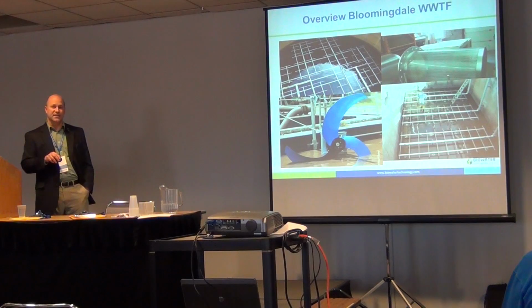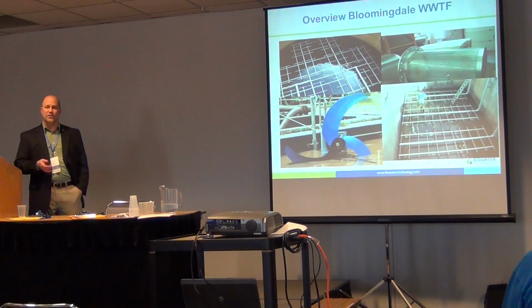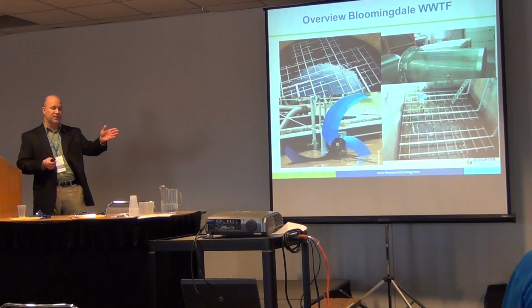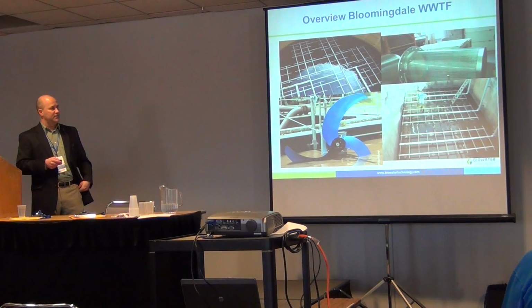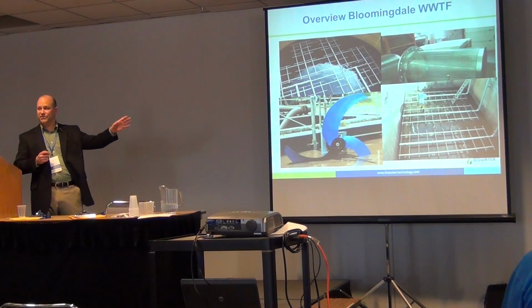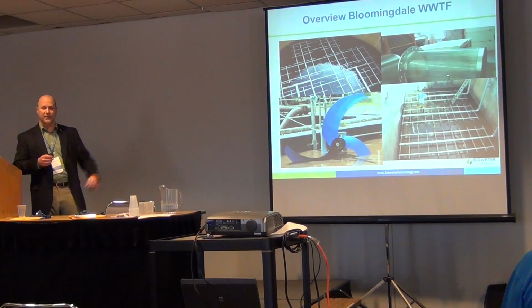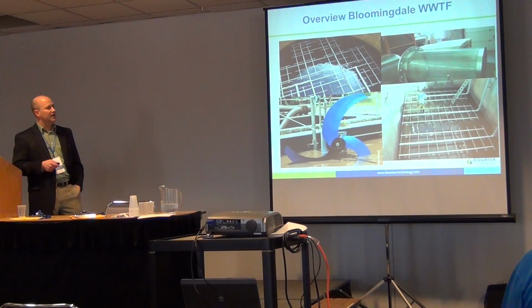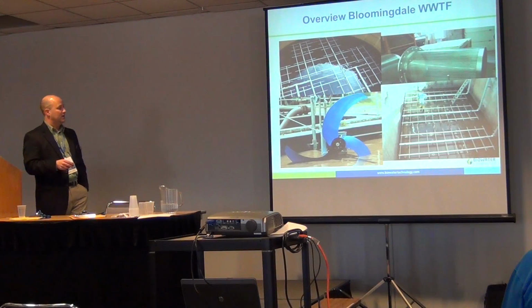And from a hydraulic standpoint, the end wall velocity, the flow coming through the plant on a rectangular tank, you don't want it more than 30 meters per hour on the back end wall. If you get a long rectangular tank and it's just gushing through, it will push all the media down to one end and block up that screen. So that's a design consideration too, the tank configuration, particularly if you're looking at an upgrade to an existing activated sludge plant. You want to make sure that the flow going through those tanks is correct, that you don't get too much velocity hitting an end wall.